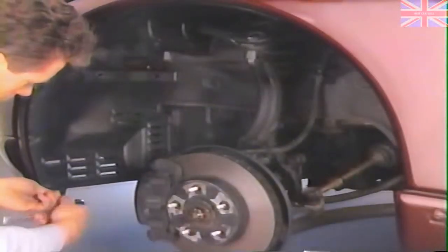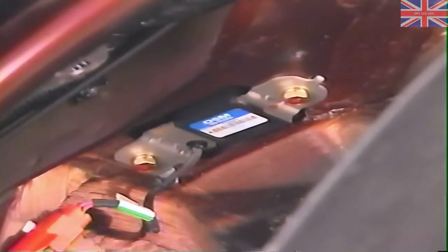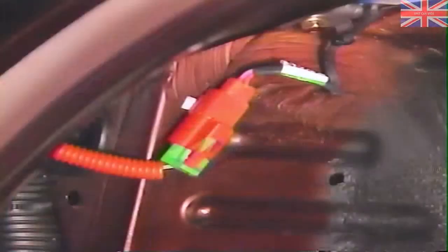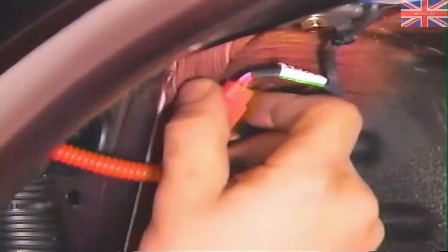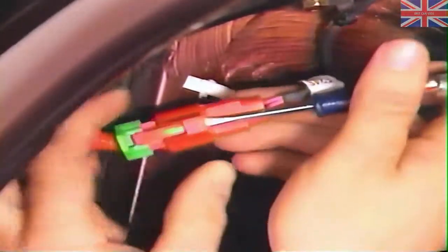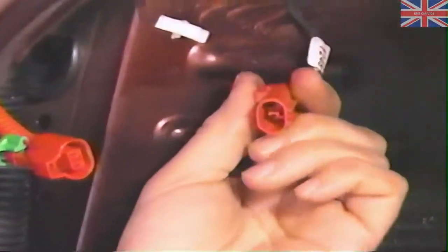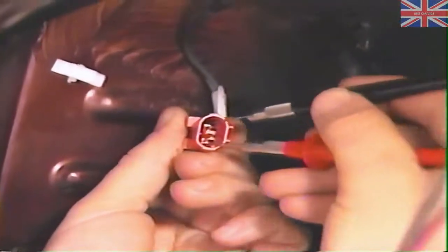We'll start by checking the sensor. To check resistance at the left impact sensor, remove the splash shield in the left front wheel well. You'll see the sensor in the upper front corner of the fender. To disconnect the impact sensor connector, pull back on the green connector lock and lift up on the red locking tab. Then measure the resistance between the terminals of the sensor.